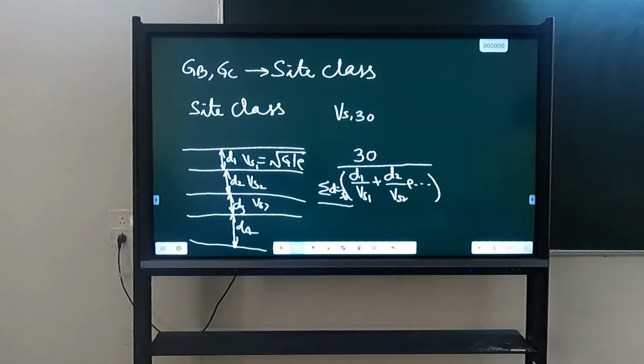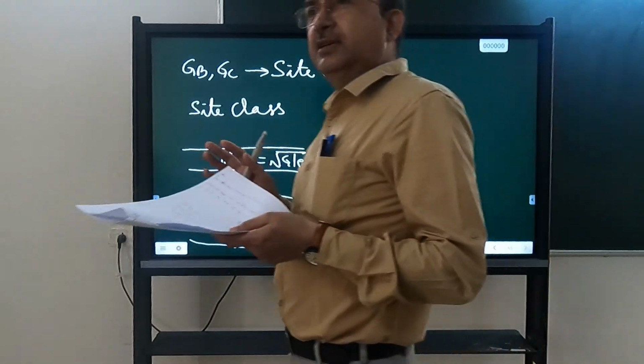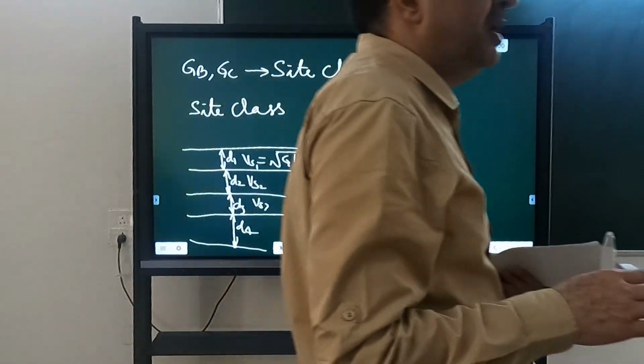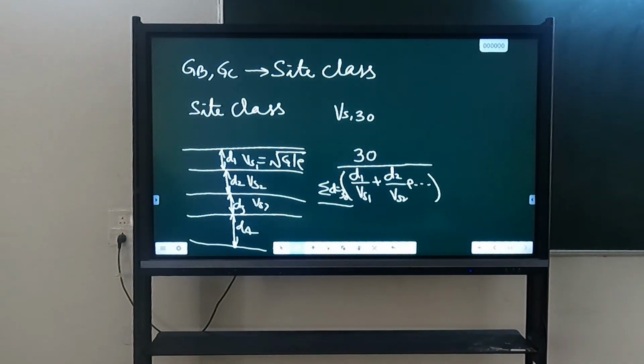So the most commonly used test is SPT, standard penetration test. Have you seen that? Even if you are a structural engineer, you should know what SPT is and how it is done. Simply we drop a weight and see how much it is penetrated. What we get is the N value. So that is always done. Whatever building or bridge you are designing, most of the time in geotechnical investigation you will get the N value. So those results are generally available.